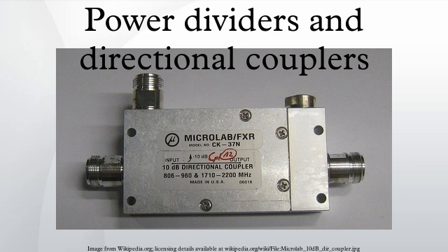Multi-port splitters with more than 2 output ports usually consist internally of a number of cascaded couplers. Domestic broadband internet service can be provided by cable TV companies. The domestic user's internet cable modem is connected to one port of the splitter. Power combiners: since hybrid circuits are bidirectional, they can be used to coherently combine power as well as splitting it.